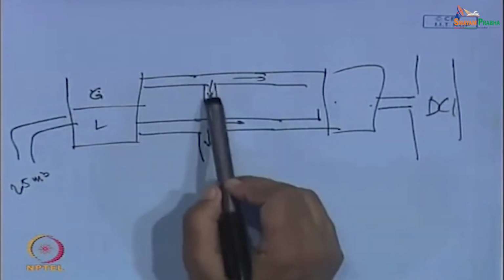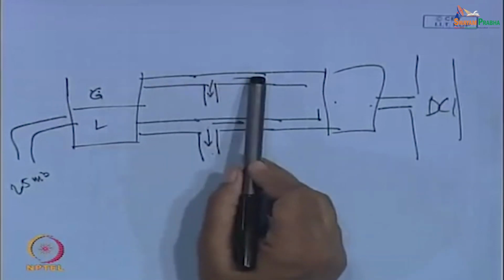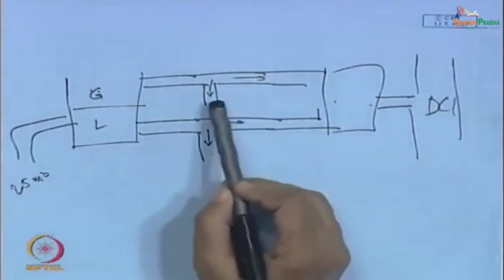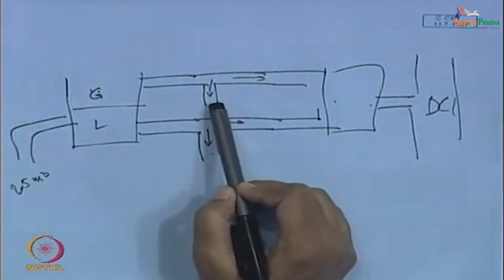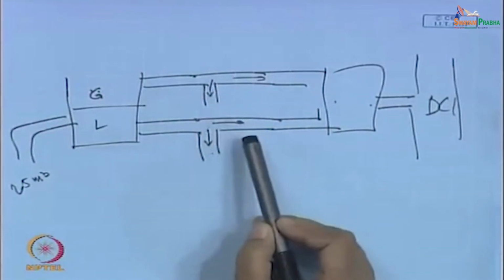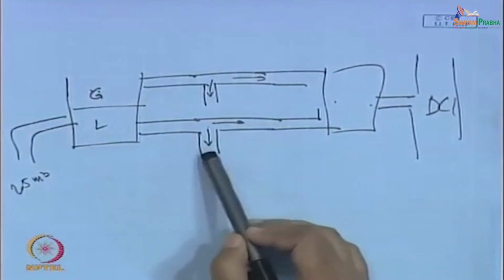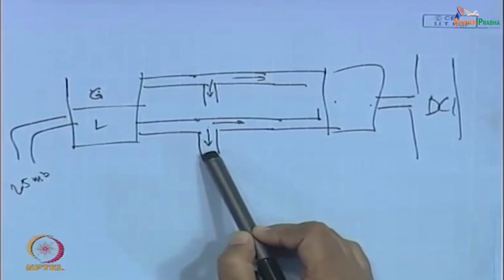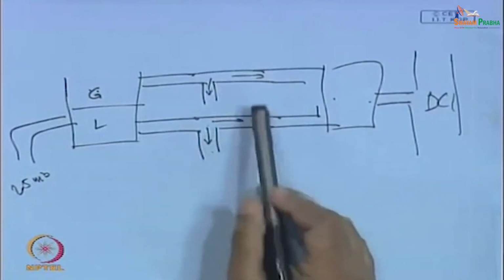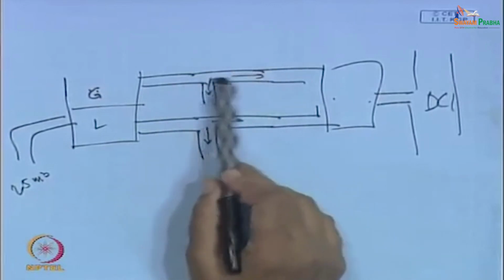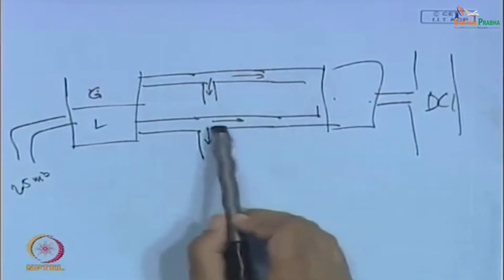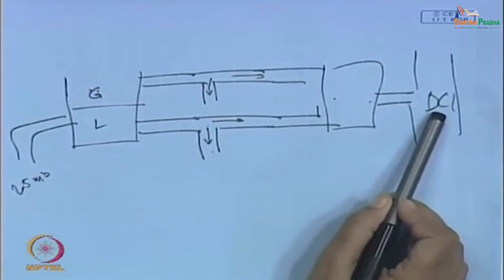Now, when only one phase is flowing, the proportions can be varied at will. There is no problem of composition changing, isn't it? Pure gas phase. Similarly, for the liquid phase also the proportions can be varied, okay, by adjusting the diameters and things like that. So, by this process we could get the amount of gas and the amount of liquid for which DC1 was designed, right.